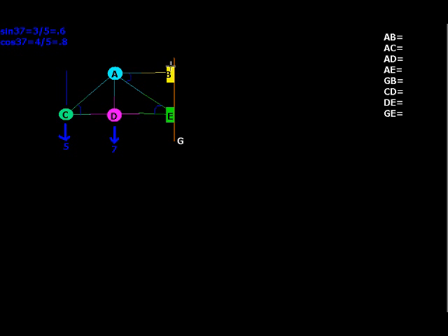If you are pushing on a bench, and the bench is anchored into the ground here, or you're pulling back on it, turn your whole head to the left, 90 degrees, say this is some kind of weird bench, well then these places where it's anchored into the ground have got to pull back, or push back. So there's going to be one more force, or actually two more forces, because there's two anchors here, that we have to look at, and those are RB and RE.